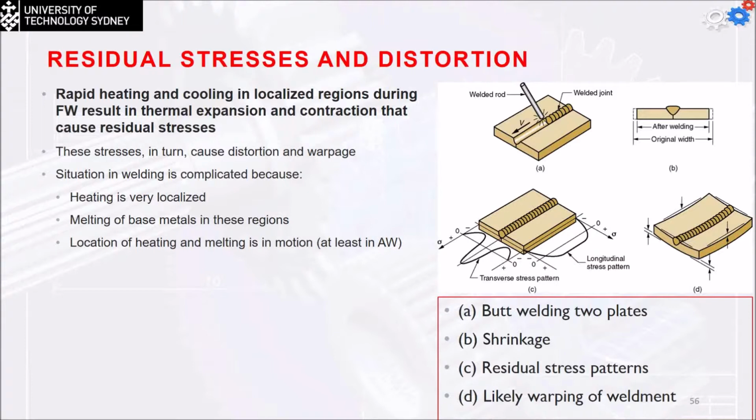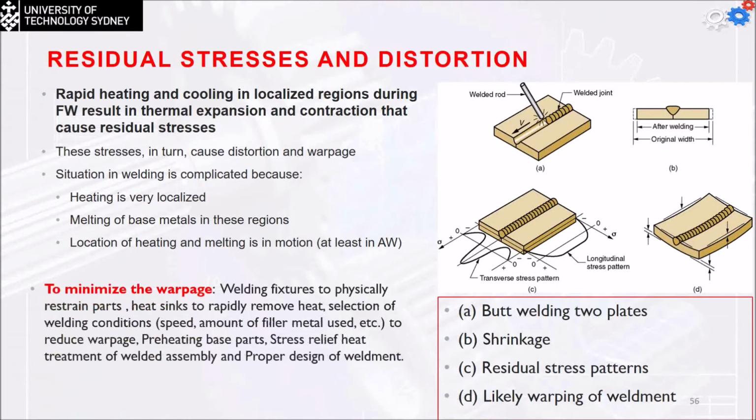The possible welding defects are, first, we can have cracks within the welding area. We can have some cavities where air bubbles are trapped within. We can have some solid inclusions, dirt, or even the flux. We can have imperfect shape or unacceptable contour. We can have incomplete fusion, and some other miscellaneous defects may occur.